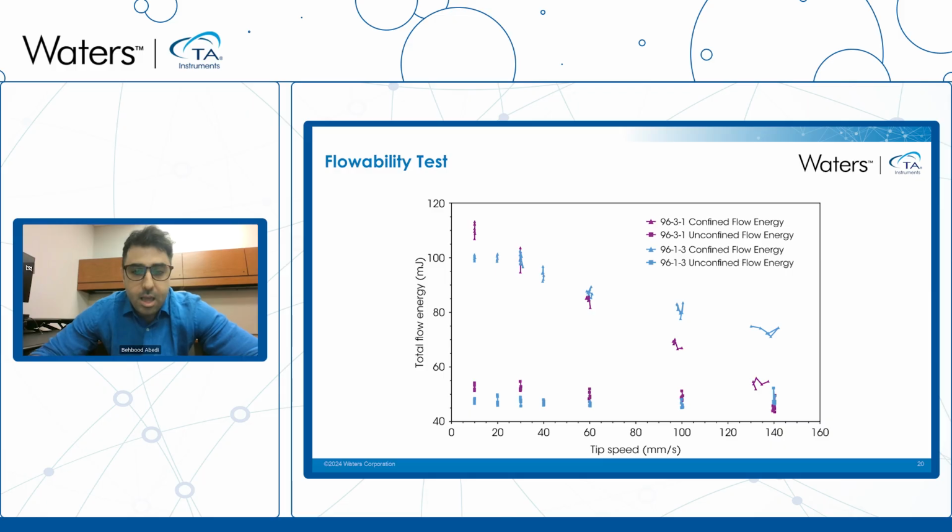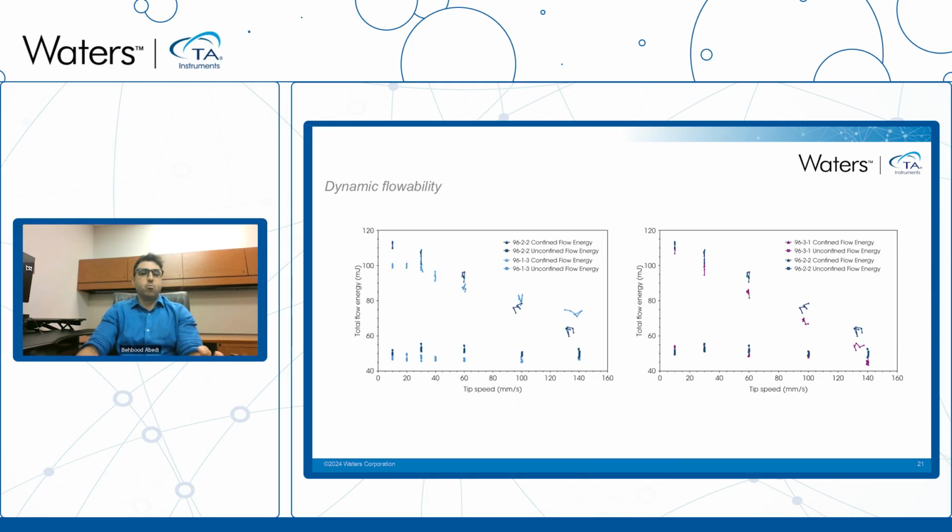So yeah, you see here also for the other compositions, the same thing. You see shear thinning behavior here, but depending on the binder content and the carbon black content, you have different degrees of shear thinning. So there's a fine line. You tune your powder so that sometimes shear thinning is desirable. You want it because of better coating, but you don't want your conductive network to disappear.